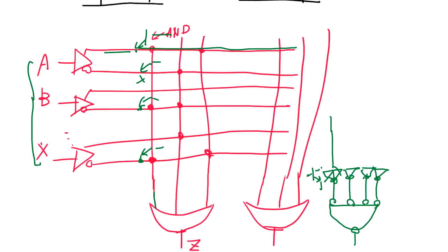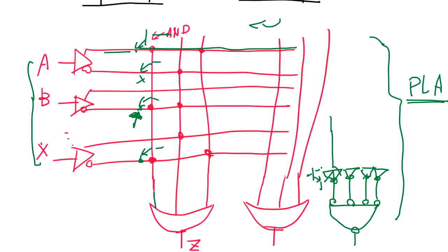Okay, so this is the programmable logic array, and if you do that for each custom chip, this is a programmable logic array. If you make this connection here by fuse, and you can blow the fuse from external power inside the chip, then it becomes a field programmable logic array. So you have a basic master logic array chip, and you program to blow fuses for each location on each chip. Then this becomes a semi-custom chip.